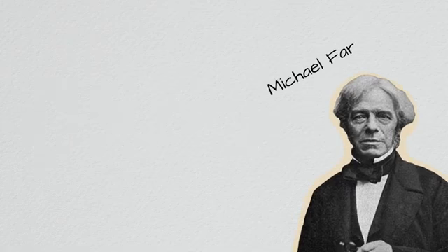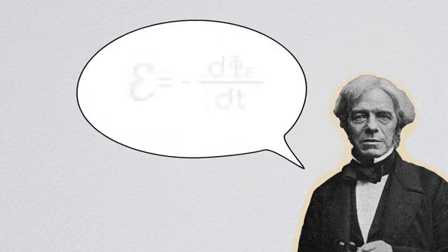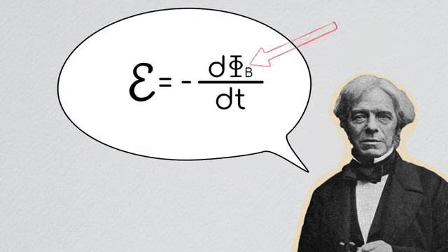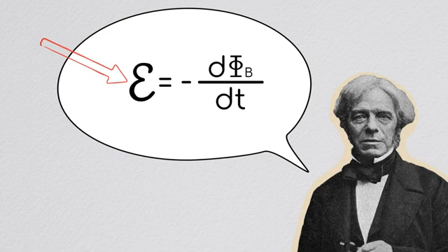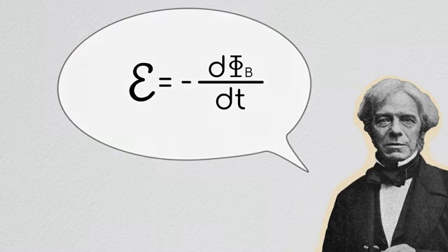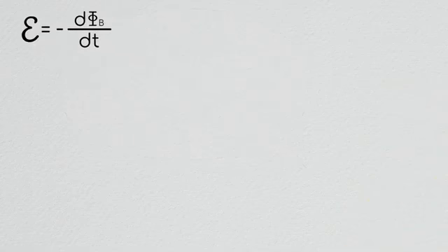Before we can move on to looking at how motors work in practice, we have to talk about one more physics principle: Faraday's law. What Faraday's law essentially says is that the flux, which is another way to say the magnetic field going through the closed loop, cannot change too quickly. If an external magnetic field going through the loop changes, an electromotive force, which is a fancy way of saying voltage, will be generated across the loop itself such that a current flows in it and induces a magnetic field which resists the changing magnetic flux.